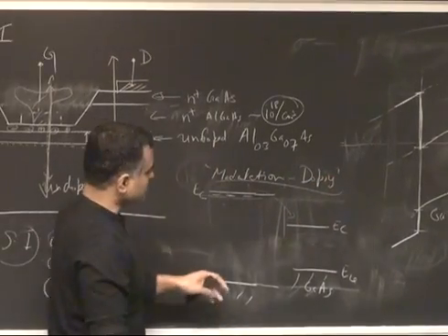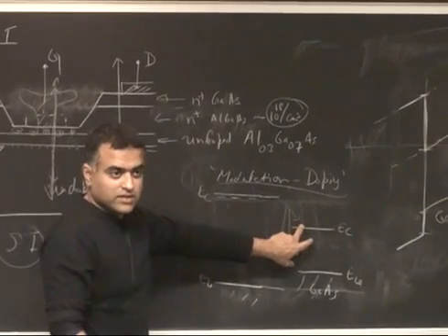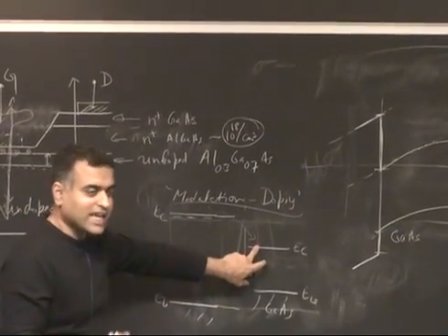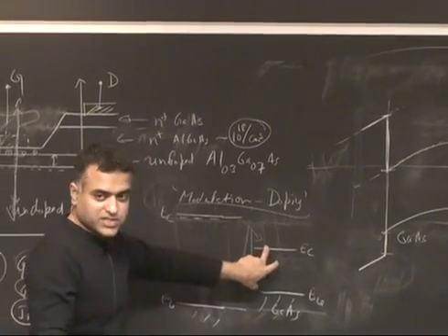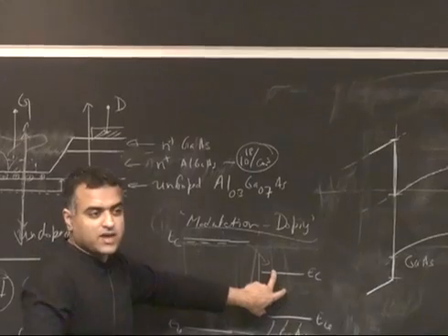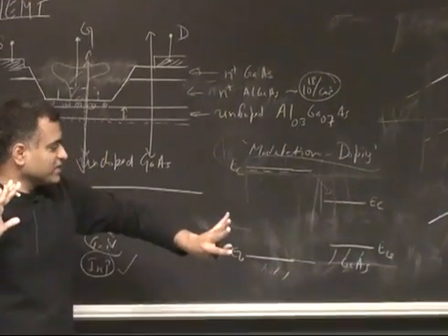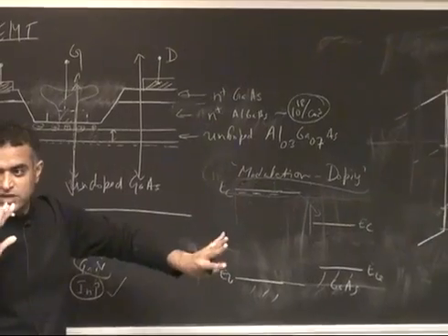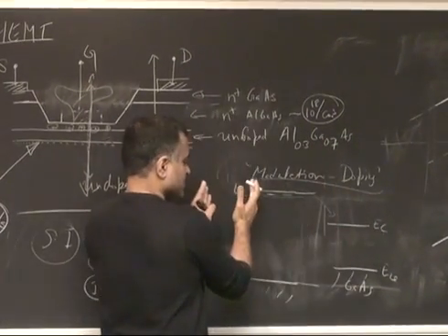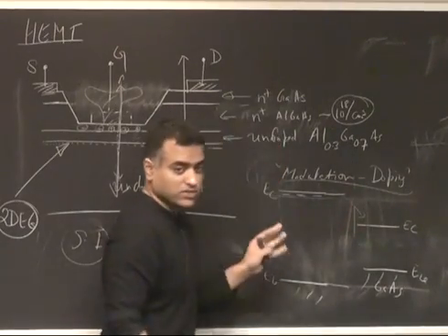All that it means is the place where the electrons are actually moving, the dopants are not there, they're somewhere else. As a result, the mobility reduction you get because of scattering from dopants is very low. You don't have much scattering. As a result, the mobility is very high, because of this region. You have removed the source of the electrons from the path of the electrons. The electrons are going to move this way, they're not going to go towards the dopants anymore, and the dopants are sitting far away, so their Coulomb potentials that scatter the electrons are very weak now. So it's modulation doping.